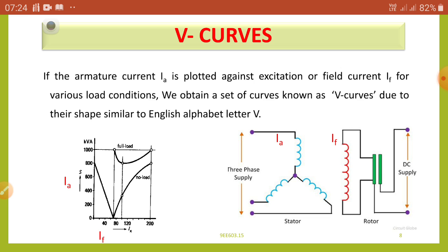Wait for 10 seconds, then note down the armature current as well as the power factor from the power factor meter. You should remember whether the power factor is changing from lagging to leading, whether it is on the lagging side or leading side on the power factor meter.